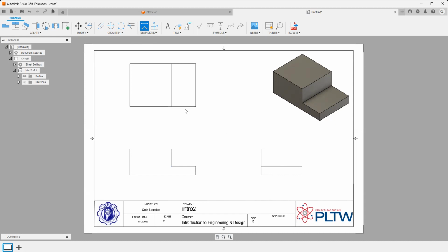So I'll need to click on the dimension tool again. But this time I'm going to clean this up a bit. Instead of clicking on the line, there are going to be some dimensions where I'm going to click on the corner. So I'm going to click on the very far corner of that object, the very far corner right here, and I'm going to create a 2-inch dimension right there. Now you'll notice that if your mouse is over the line itself, it'll come in at an angle. We don't want that. We want a completely horizontal line. So I'm going to create a dimension right here about halfway between both objects. And then I'm going to create another dimension from this line right here. I'm going to place it right about there.